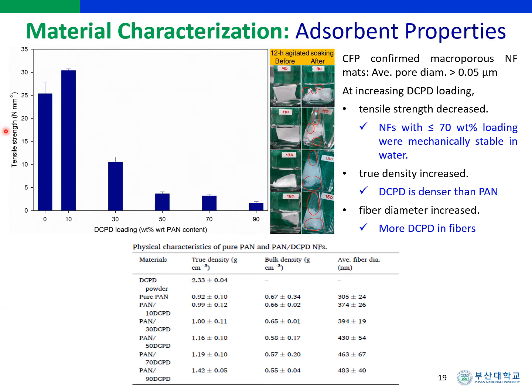Considering their ease of handling, high adsorbent powder loading capacity, and relatively suitable mechanical strength, composite PAN nanofibers with less than or equal to 78% DCPD loading were more apposite to be applied in strontium adsorption. The effect of DCPD loading on the physical properties of PAN-DCPD nanofibers is summarized in this table.